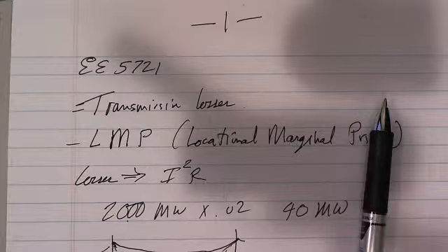Let's further point out that if it's January and there's a 40-mile-an-hour wind and the temperature is already 10 below zero, you can heat the lines up a little bit, because the temperature of the line is not going to get too warm. And what will happen in many cases is that the operations group of a power system will take that into account during winter weather, low temperature, high wind.